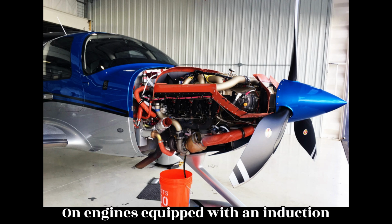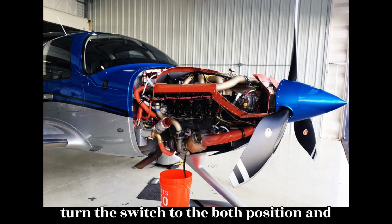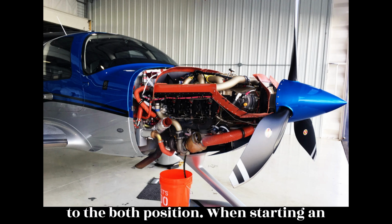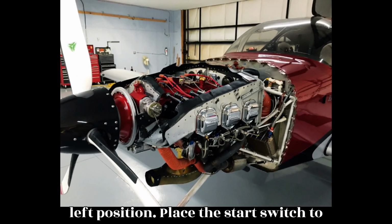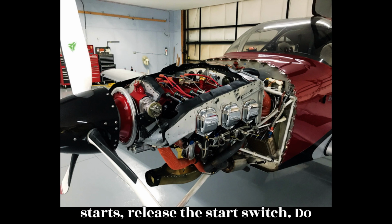On engines equipped with an induction vibrator, shower of sparks, or a magneto that incorporates a retard breaker assembly, turn the switch to the both position and energize the starter by turning the switch to the start position. After the engine starts, release the starter switch to the both position. When starting an engine that uses an impulse coupling magneto, turn the ignition switch to the left position. Place the start switch to the start position. When the engine starts, release the start switch.